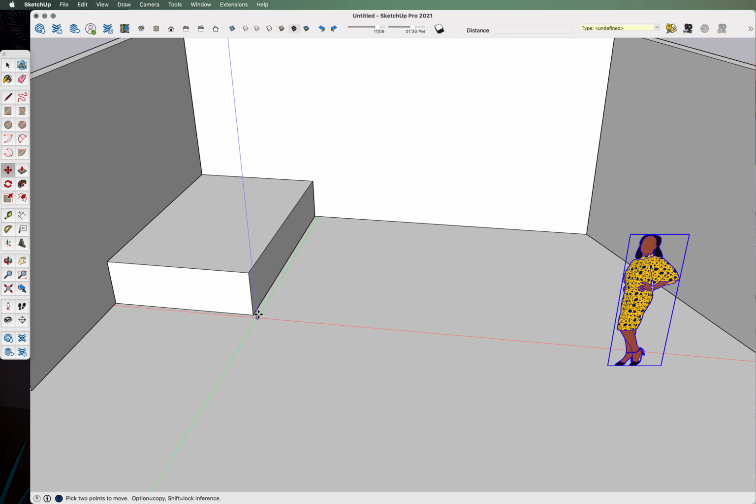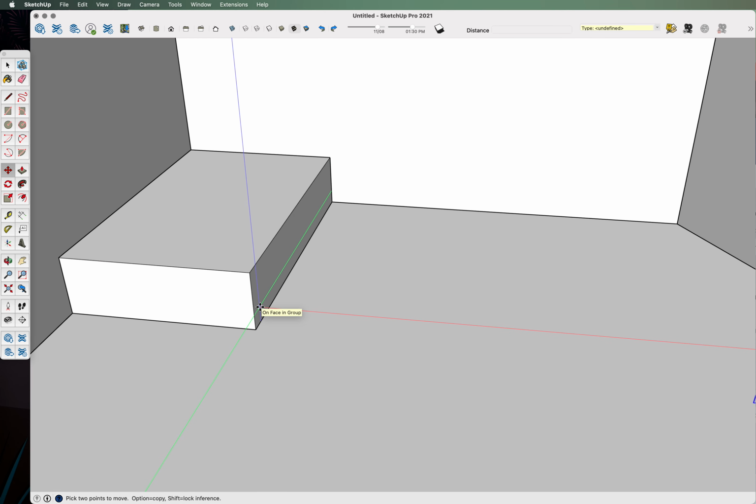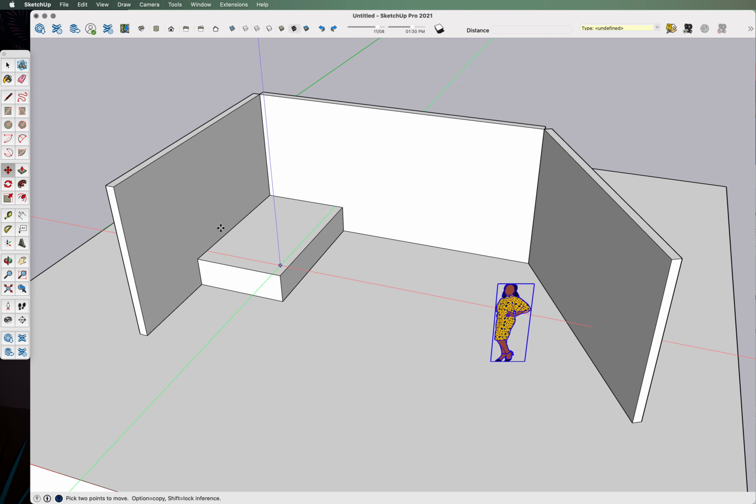Okay, we are looking at a 2-foot platform, so for the sake of ease of actors getting up, we're going to simplify this and make the steps each 6 inches in a rise, and we'll do 12 inches as the tread depth. So let's keep that in mind. We'll need 4 full risers or 4 full steps to get up to the top of this, including the deck itself. So we might end up eliminating one of the steps after we've made it. So let's just focus on the very first step.